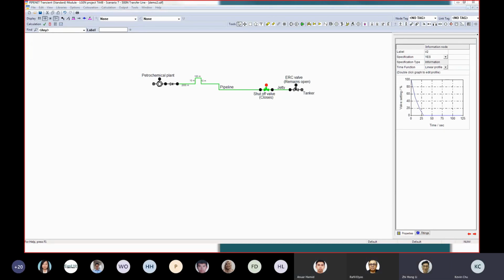There's one. What is the difference we will experience in choosing the CV value in the PCV or other parameters? So I guess maybe it will give rise to a different pressure drop, a different flow rate with respect to different pressure drop, because different parameters are used for the CV.